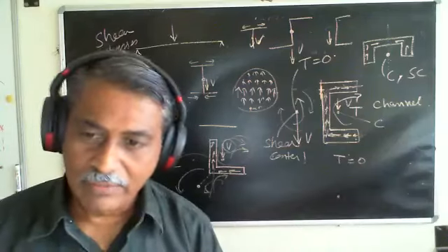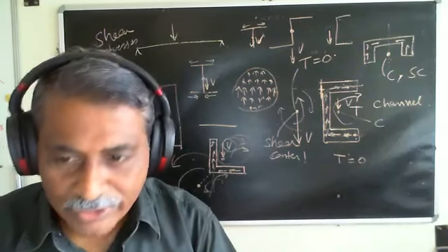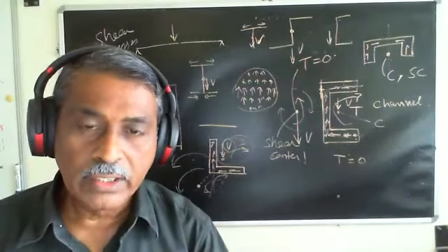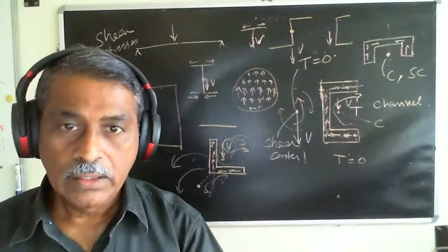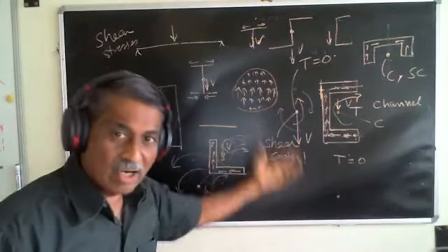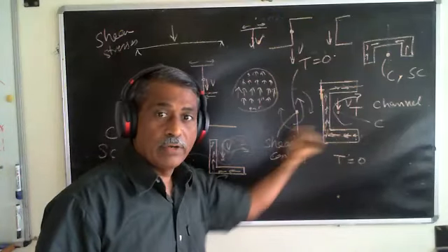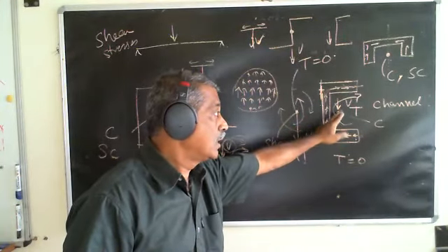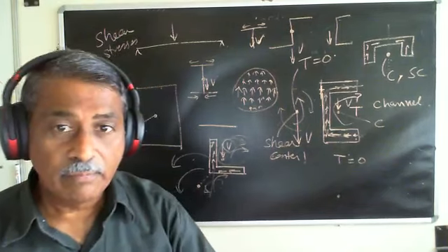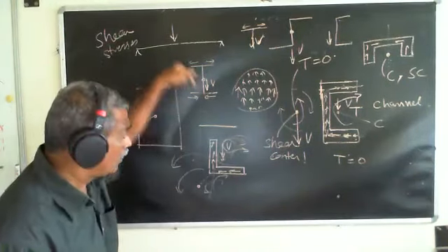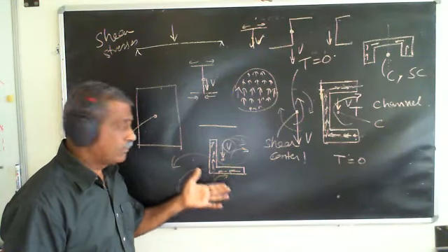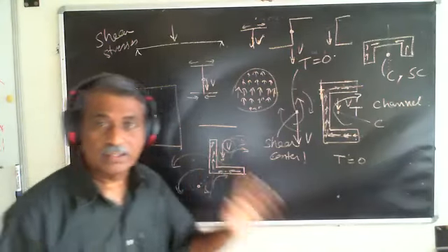Because you are familiar with free body diagram. Okay, folks. So we learned two concepts today: the flow and how to deal with the thin, hollow cross sections for torsion. The other is thin sections, or it need not be thin sections. How do we now differentiate between application of transverse load at the centroid and the shear center? Okay. Remember, this is very different from whatever we did earlier, where we applied load like this. Here, I want you to figure out which is the direction that I have to take in order to offset as far as shear center is concerned.